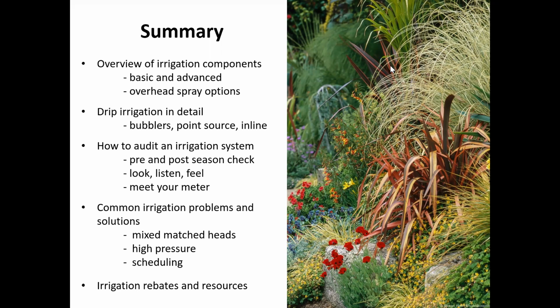As water is going through that drip line, it's going to activate that leak indicator to mist. So if you have a leak on any area on that drip line, that water is going to be moving through that drip tube. So that one should be sufficient. You really only need one per valve on the drip.